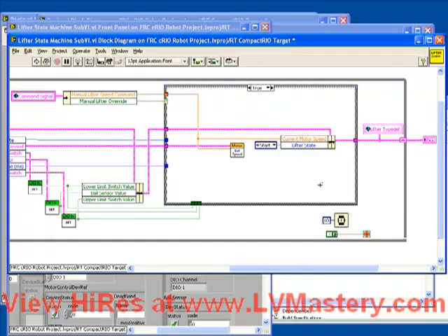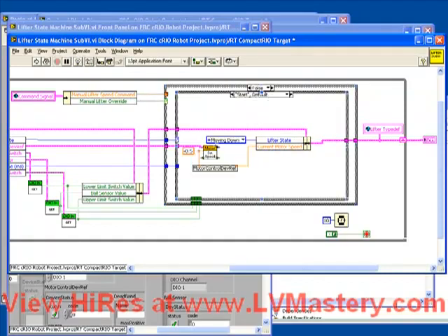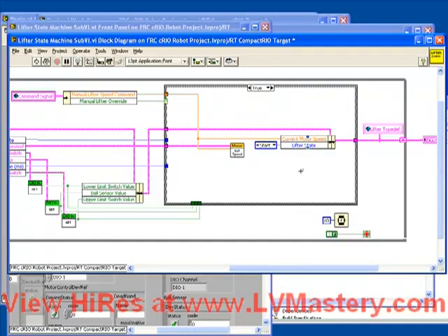Now, why would we want to do that? Well, it's important when we go into override mode and when we come out again to know what state we're in. If we're up, we don't want to think we're in the down state. If we're down, we don't want to think we're in the up state or waiting for ball. If we put the lifter into the start state here, then if manual lifter override went false, when we came into this case, we'd immediately automatically go back to the start case, which means we could start our sequence again from a known position. So it's really important to take care of this kind of housekeeping behavior when you're changing things based on external values such as the command signal.